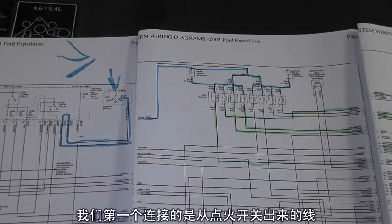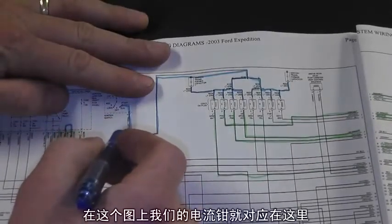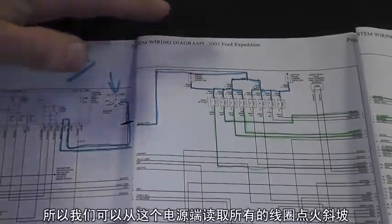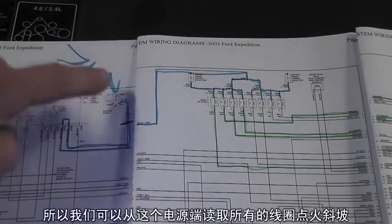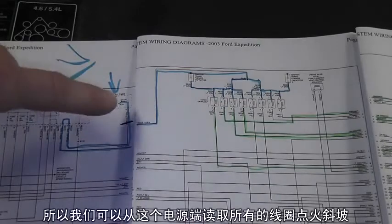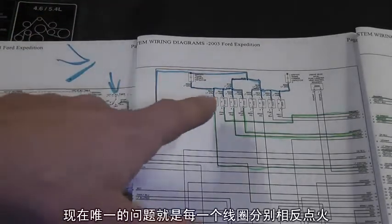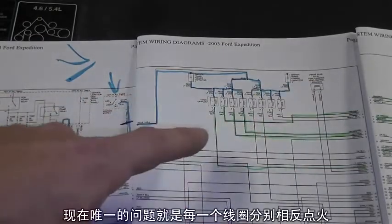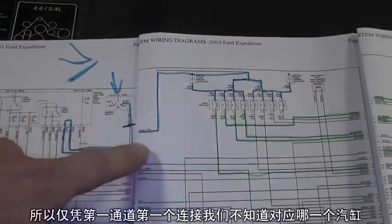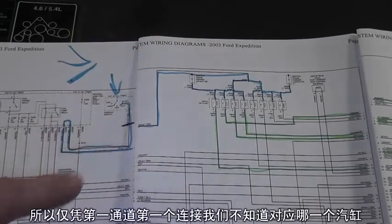Okay, so our first connection, we are connected to the wire that comes out of the ignition switch, where basically in this picture our amp clamp is right here. So we're going to read all of the coil current firing ramps from that feed. The only problem with this right now is that each coil is going to obviously fire individually, and so we're not going to know which cylinder is which by this first channel alone.